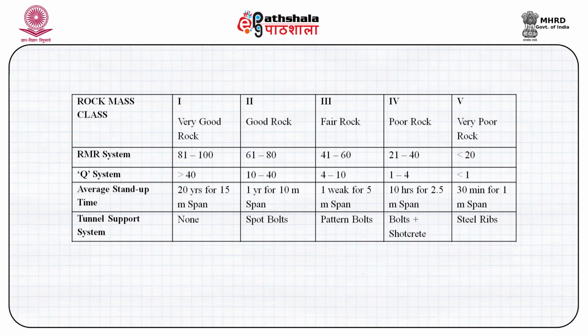So as rock mass quality deteriorates, the stand-up time suddenly goes down, even for a smaller span. In this case, you may have to install spot bolts wherever required.